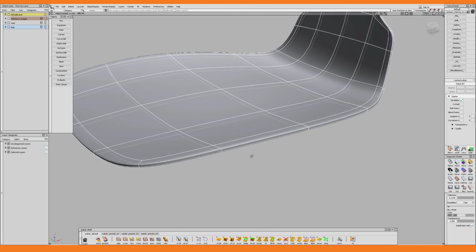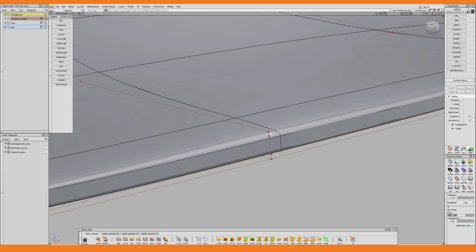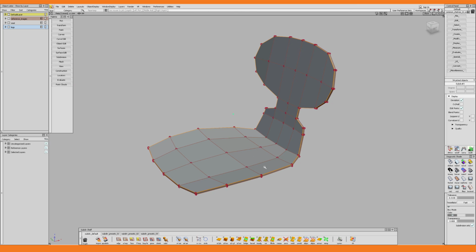And I think that the most simple and straightforward way of doing this is to simply redo the whole extrusion process that we did earlier. Before I can do that, I however need to take a few steps back. I choose Pick Face Loop. And then I drag select in the direction I want the loop to run. So now you see I selected all the faces in this loop, all around the seat.